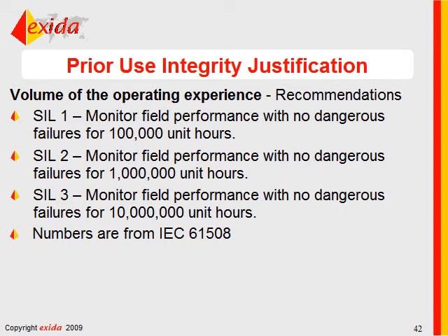Another question. What about manufacturer declaration of conformity? How much trust should we give it? My personal answer: no trust, 0. Why? I'm not convinced that anyone who doesn't work on 61508 assessment full-time can do a good enough job, especially for SIL 2 and SIL 3. Maybe manufacturer's assessment for SIL 1 is a pretty good thing.